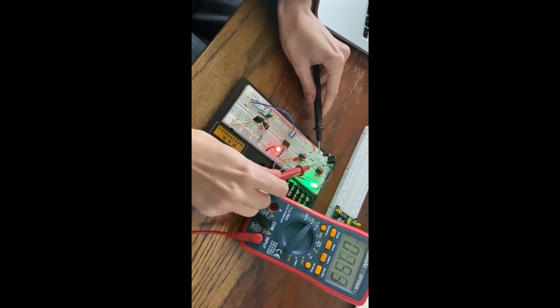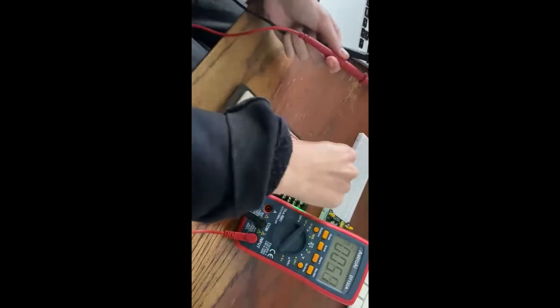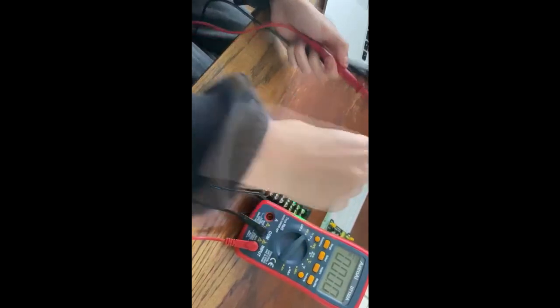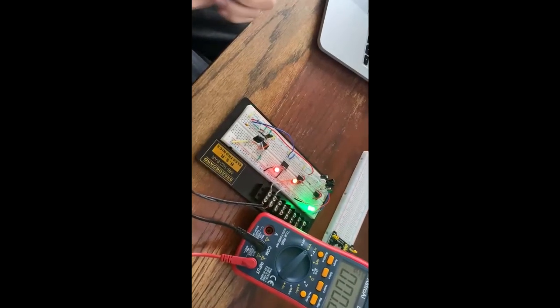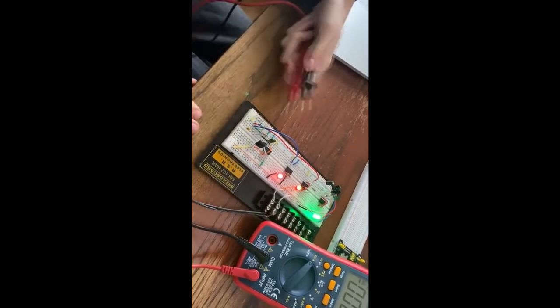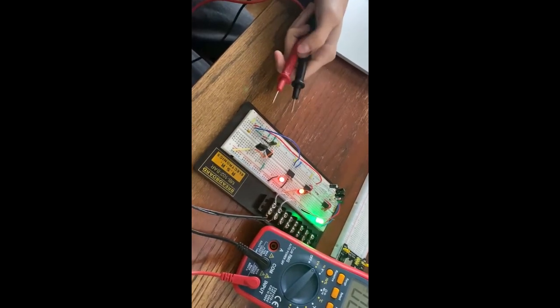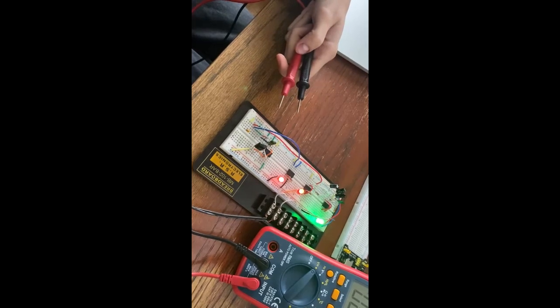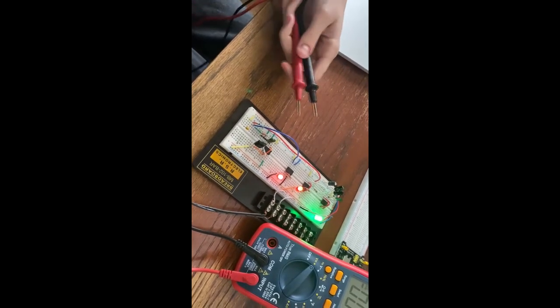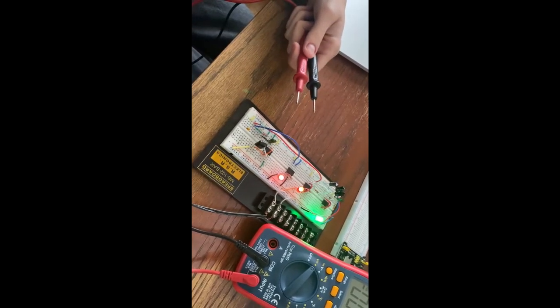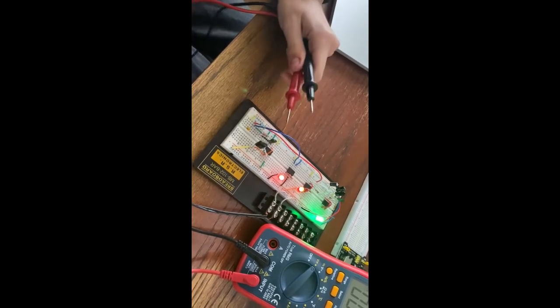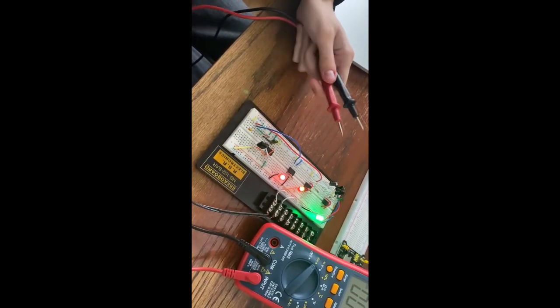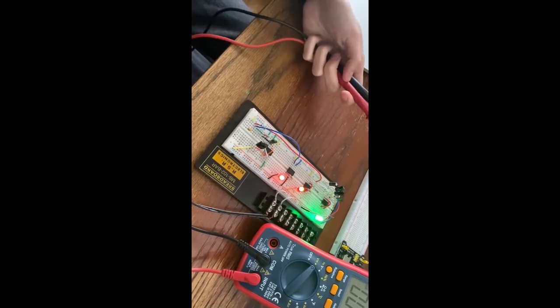Almost 10 volts of power. I've designed a signal generator using this circuit that produces a sinusoidal waveform. Another 555 IC timer is used. This timer produces a square waveform that oscillates between high and low in astable mode. Using an RC circuitry, I have determined the frequency to be approximately 7.2 kilohertz.